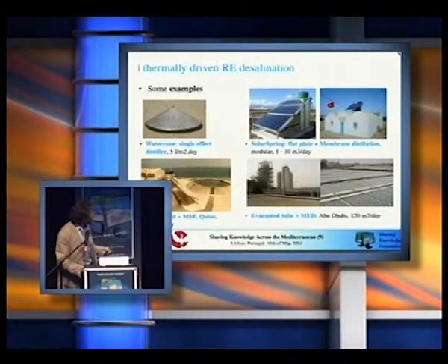Moving down, we have a project which is from the 70s or the 80s already, where the solar collector is a solar pond. In a solar pond, we can store heat in the bottom layer of a pond by establishing a salinity gradient in this pond.